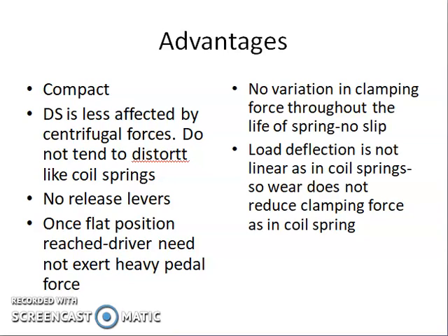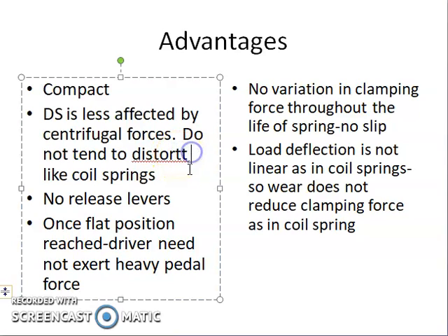So what are the advantages of this type of clutch? It is compact, and the diaphragm spring clutch is less affected by centrifugal forces, and they do not tend to distort like coil springs. You don't need to have release levers, and once the flat position is reached, the driver need not exert heavy pedal force. Whereas in the case of the coil spring, the force the driver applies is proportional to the deflection of the coil springs. Here, once the flat position is reached, you need not exert heavy pedal force.